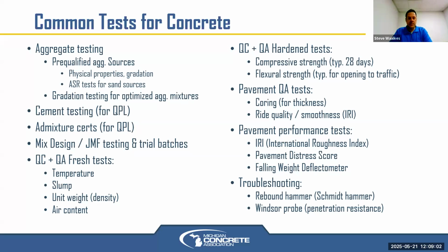So the fresh tests, typical ones: temperature, slump, density, and air. And then the hardened test, typically just strength is the most common. There are others that we can do on the hardened concrete as well.